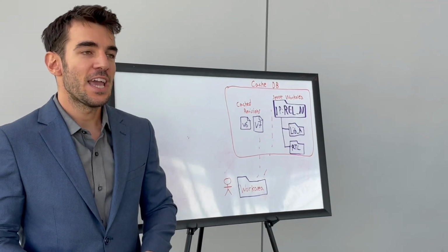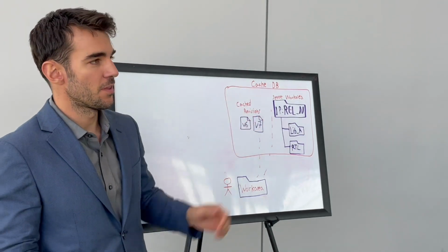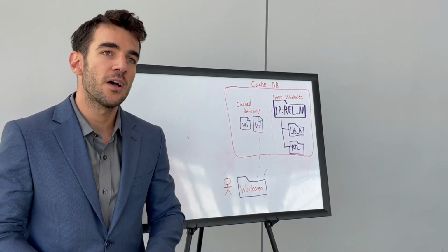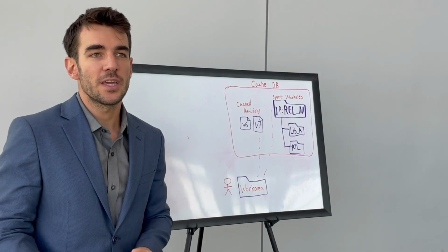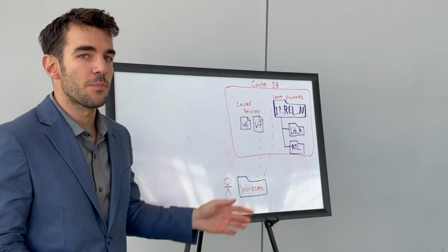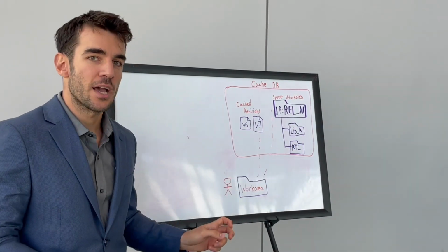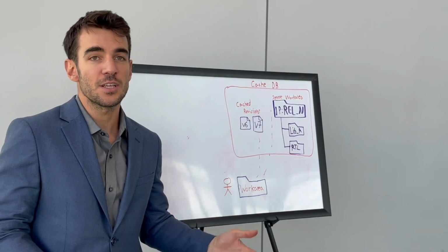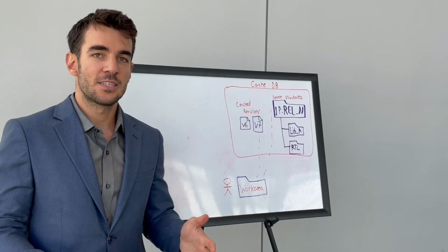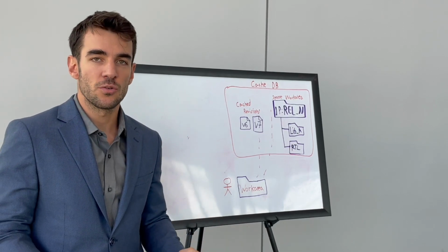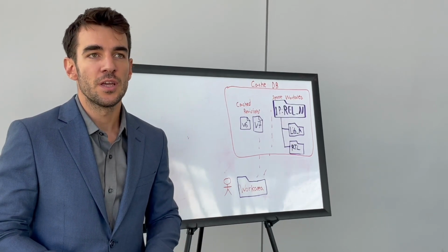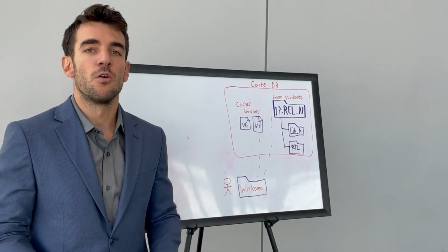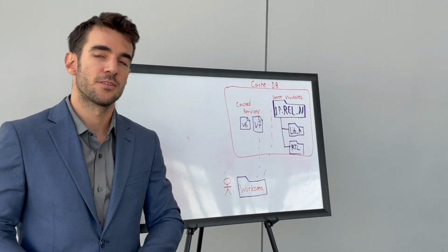So user A might be a consumer of this IP, so they will be sparsely populating the IP in their work area, but user B might need to tweak it, so they would be populating this IP in the traditional links to cache approach. Again, not consuming extra disk space with the links to cache, but the sparse populate is optimizing the population, the sync to the repository, because it is a single link pointing to the IP instead of tens of thousands of links pointing to the individual files.